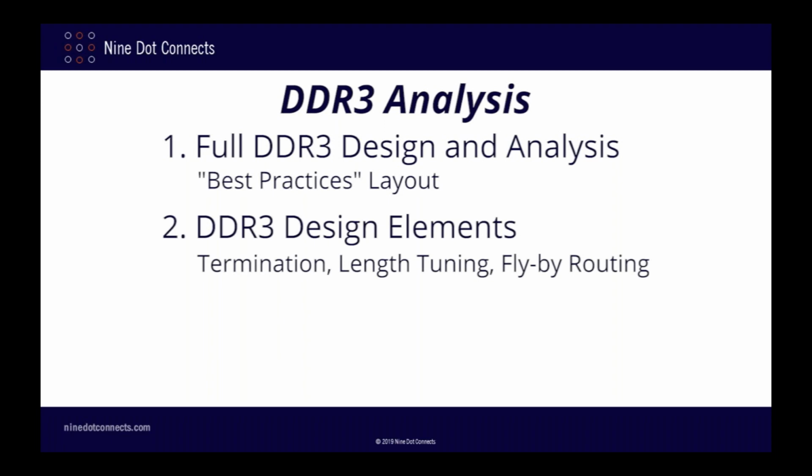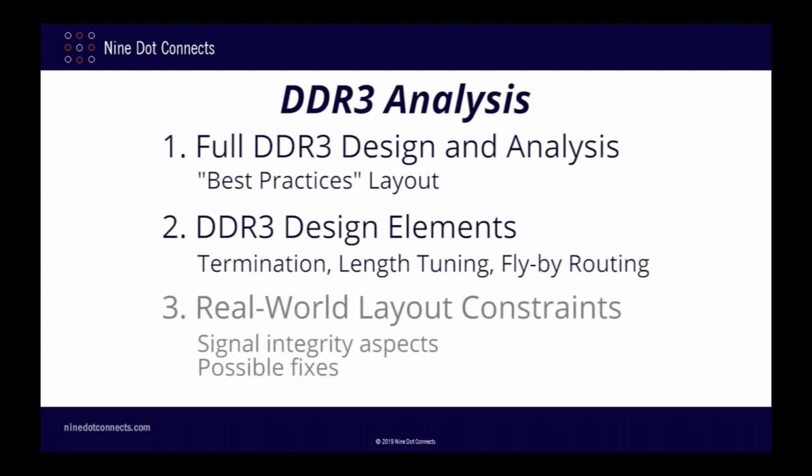I'll then look at some of the design elements that are critical for DDR3 operation, such as the need for termination and length tuning. I'll also examine the issues surrounding the use of flyby versus T-branch routing. And in the course of these examples, I will also explore some of the real-world implications caused by common constraints and other issues that might force you to make trade-offs during your layout.